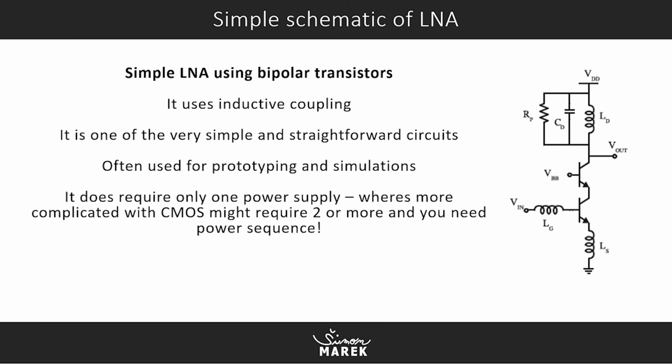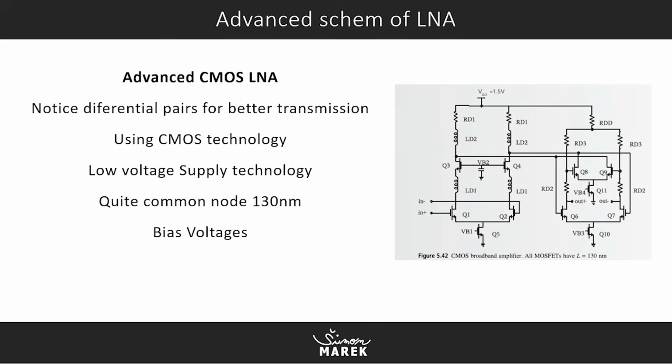It does require only one power supply, oftentimes, and it does not require any power sequence compared to more advanced CMOS integrated circuits and LNAs, which typically require power sequence.